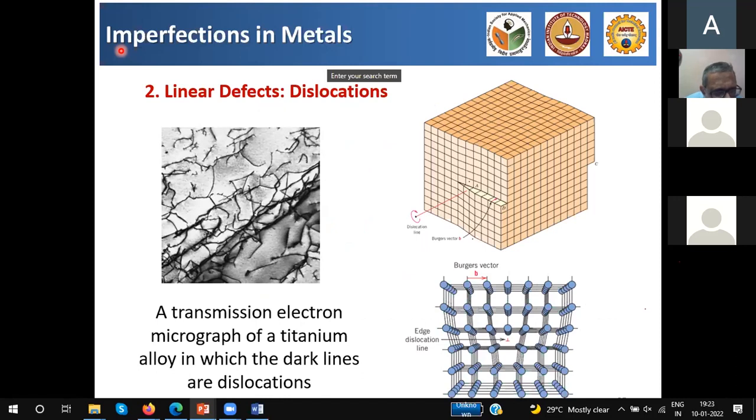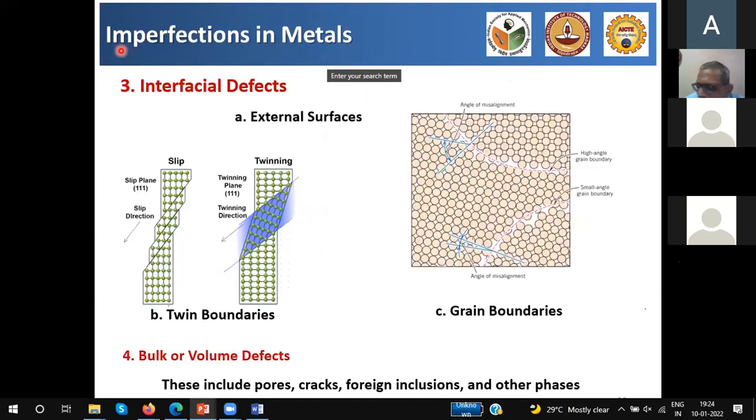And today it is possible for you to look at these dislocations and get their signatures by looking at them in the transmission electron microscope. And it's possible to look at the material and recognize that these are the dislocation signatures that are there, and the movement of these dislocations is the basis for various models that are developed from a micromechanical standpoint. So when you agglomerate all these dislocations, you have other signatures like twin boundaries, and grain boundaries of various types.